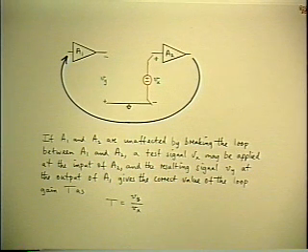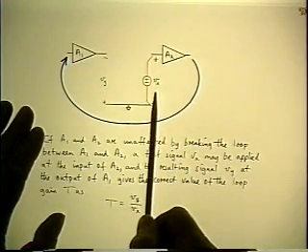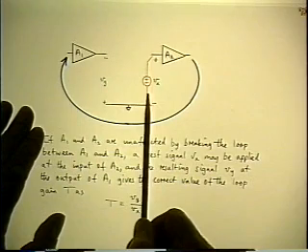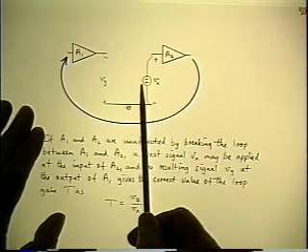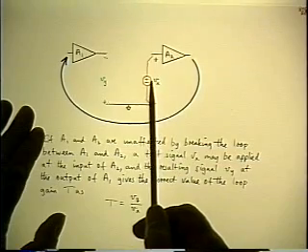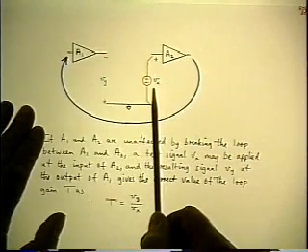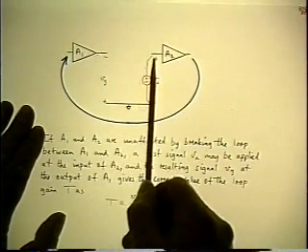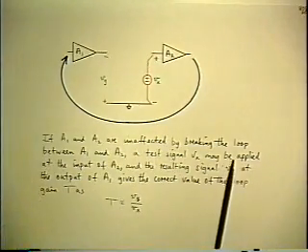Now I'm going to make another modification, which in some ways is even more important than that. Looking ahead to where we actually want to make this measurement. Again, I mentioned this in the introduction, but it's worth going over again. The T is the fundamental important quantity. So we're certainly going to want to make a measurement of it directly on the breadboard when we get to that stage in the design. And you can implement this technique directly on the breadboard. You can break the loop, and you can apply an AC test signal and measure what comes out the other end. But there's one step you have to do in between.